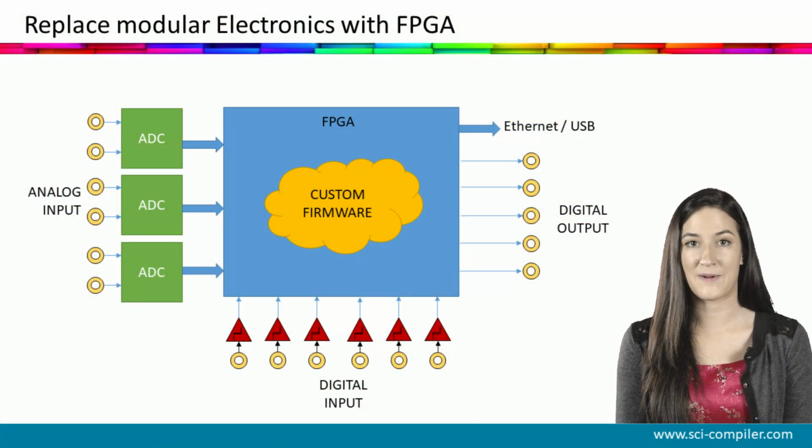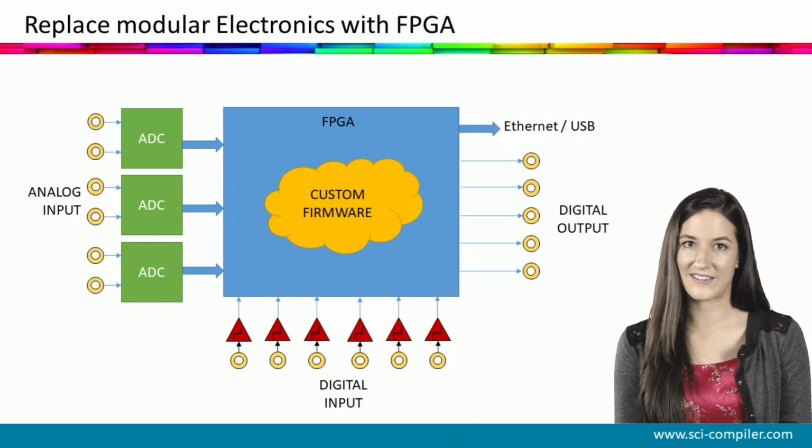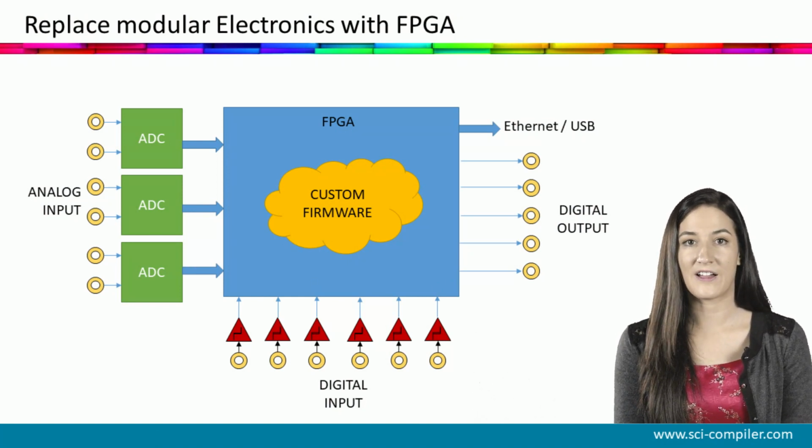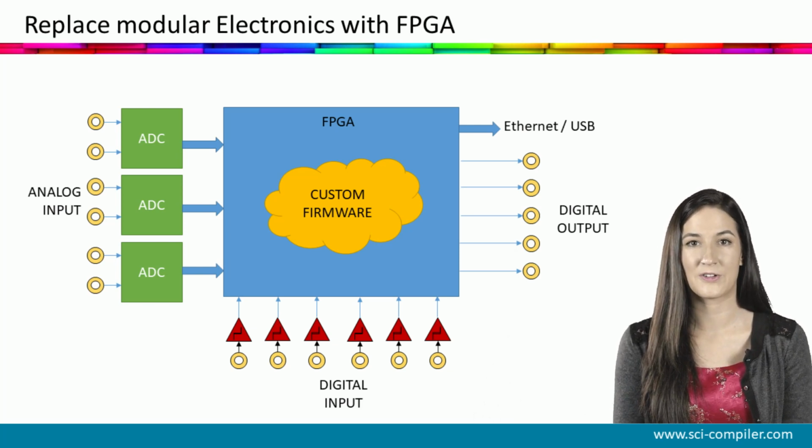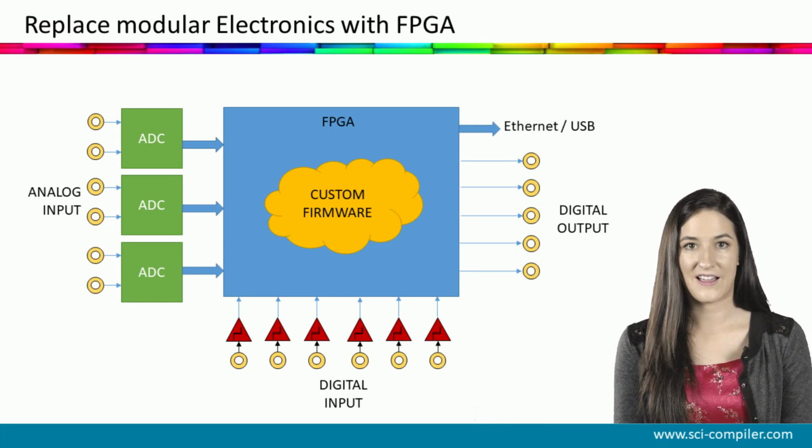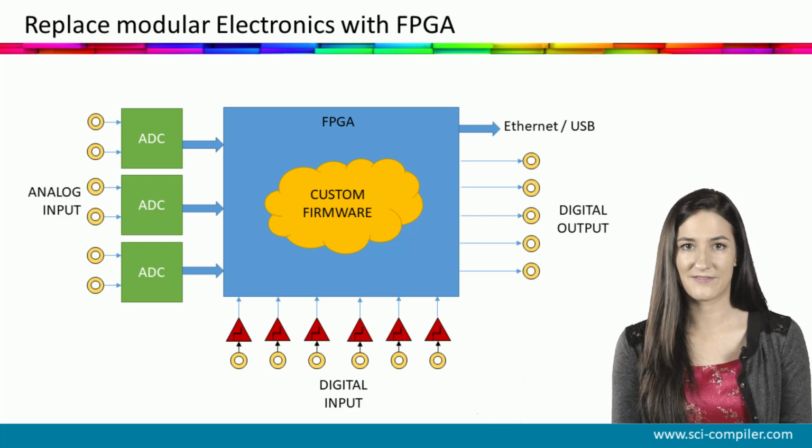Within an FPGA device, any bespoke logic or processing algorithm can be materialized by coding it in a specialized programming language. Traditional setups, crammed with hundreds of logic modules, multi-channel analyzers, and digitizers, can now be elegantly consolidated into a single board. This board utilizes ADCs to digitize analog signals, manages discriminated signals through digital input-output, and employs an FPGA to execute logic functions and manage data readout with precision and efficiency.